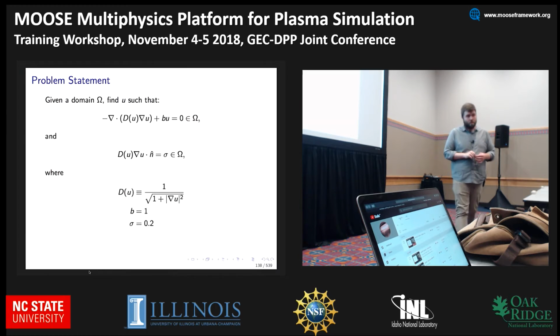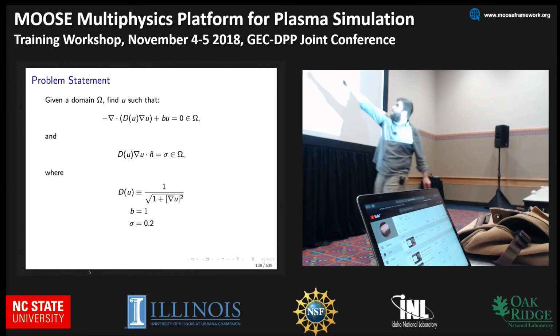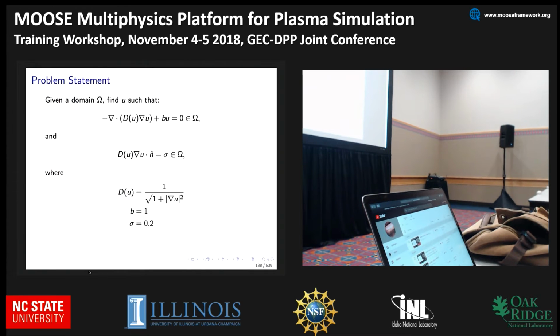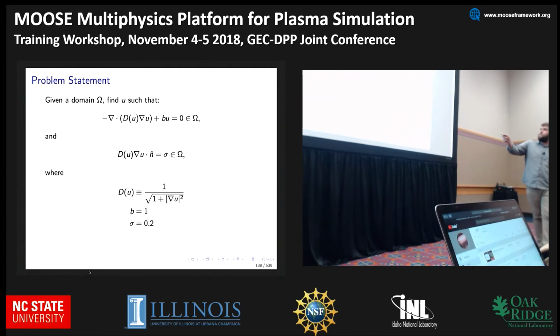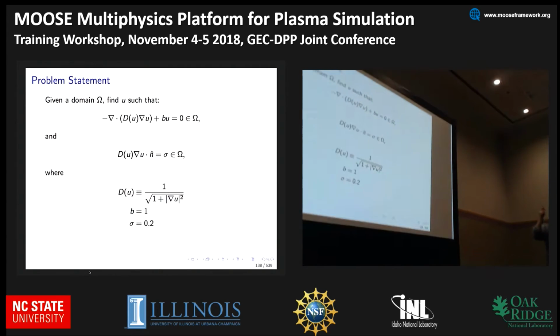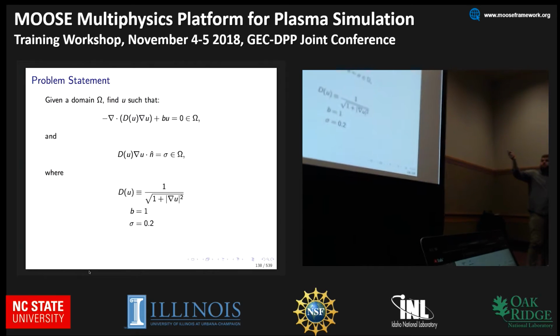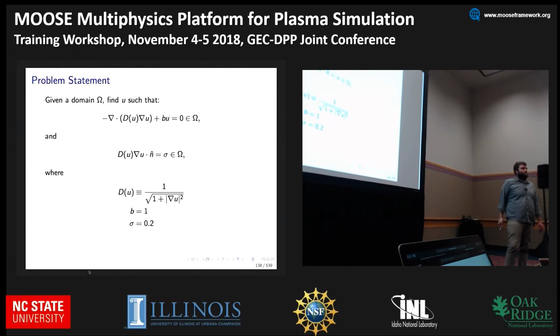So that's kind of the trick. So add u dot n. You know what that term equals. That term equals sigma. So your weak form term in that case is this times your basis function. So it's sigma times your basis function. So you just use sigma. That's the trick for that term. And the diffusion kernel that you inherit from.